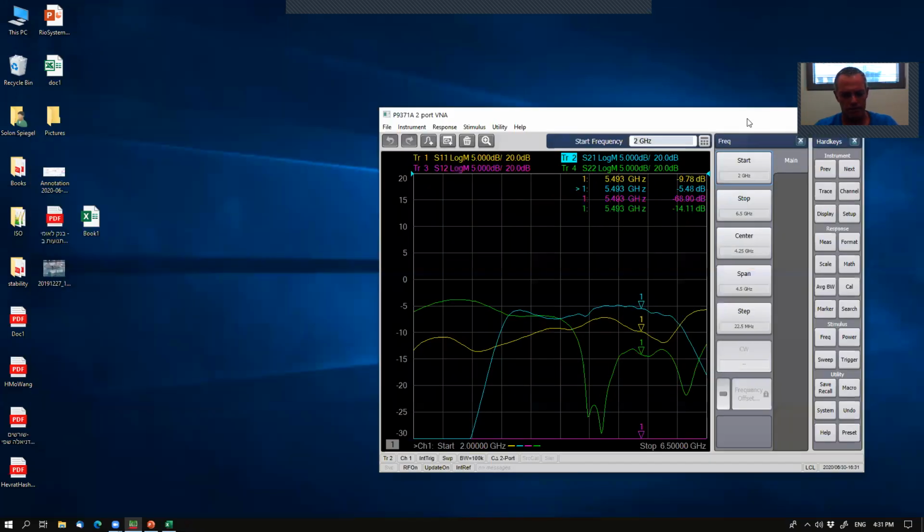The control interface for the CoreIC, because we understand that it is not sufficient for the customer only to be provided the IC. There are many aspects you have to provide to them. You have to provide the correct control words. We understand that isolation is critical. Might be one thing that is calibrated at the lab and might not be the same calibration correction words in the real system because of coupling, the coupling matrix of the antenna that is present. So there are different control words that have to be applied.